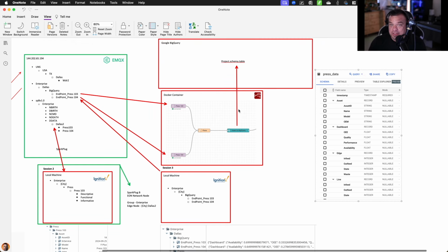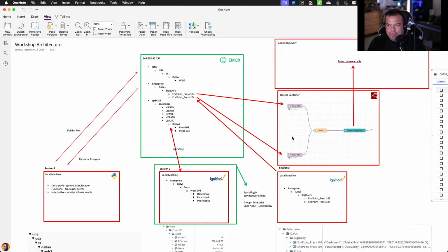And then in this case, we're using Node-RED actually to consume it. We could have used Cirrus Link modules to do the streaming. We could have used HiByte. There's a whole host of ways we could have done this. I chose to do it in Node-RED for the workshop so that I could show each of the individual steps. I could show the consumption, the parsing, and the insertion. If I'm using a commercial product to do this, I can't really show you these 3 steps. They're going to be hidden inside of a module. And so I wouldn't be able to show you the mechanics of those 3 steps and then the insertion into the table. All right. So let me show you how that looks now.